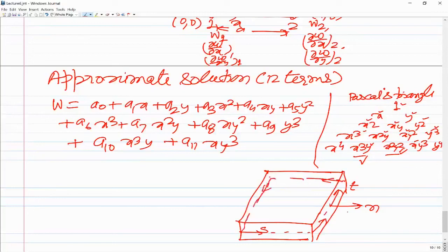So on this face, where n is along the positive x direction, we are assuming that there is a positive boundary force Vn. So this is your Vn, and then there is a positive moment about the negative t direction. So you have the moment like this. Why I have taken it like that is so that the potential of both of them is negative. So this is your actual Mn.